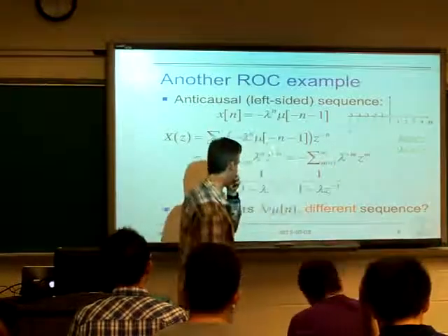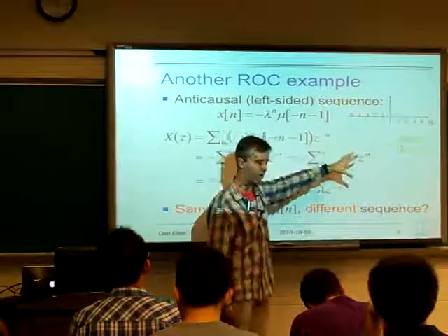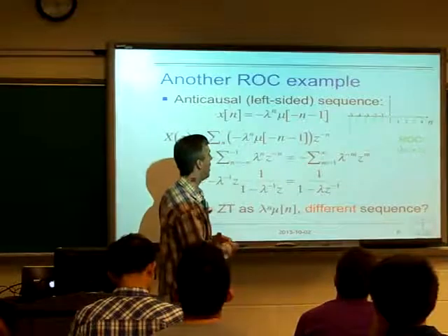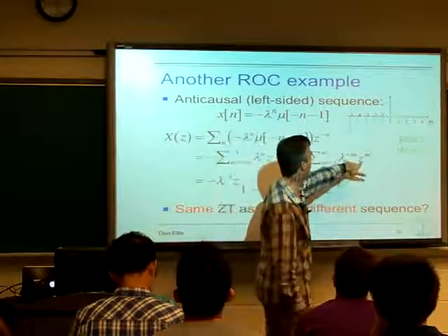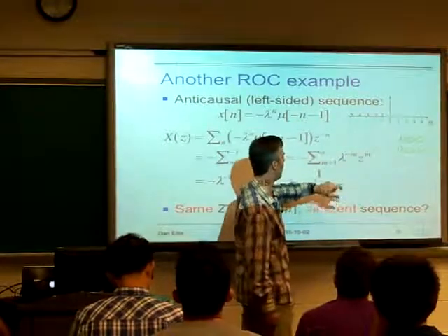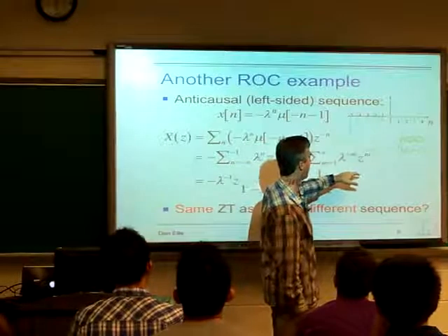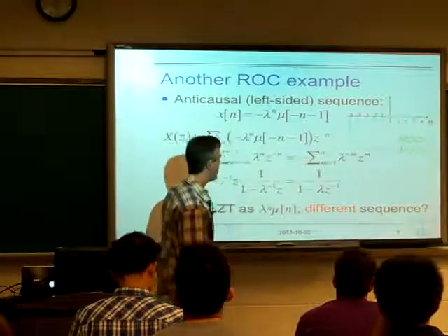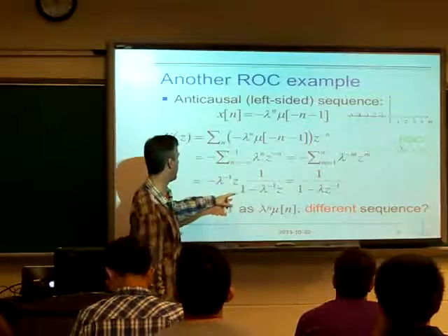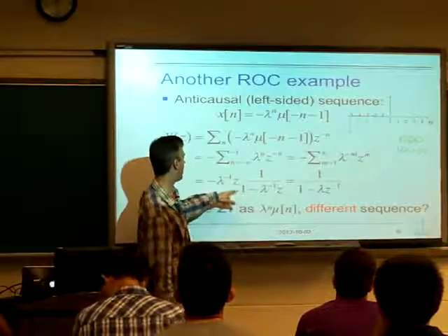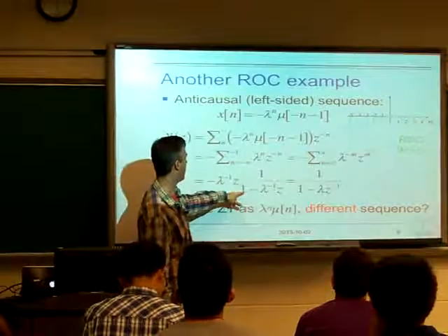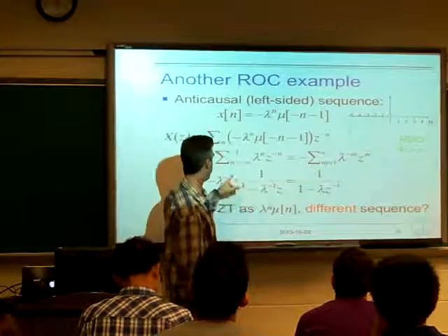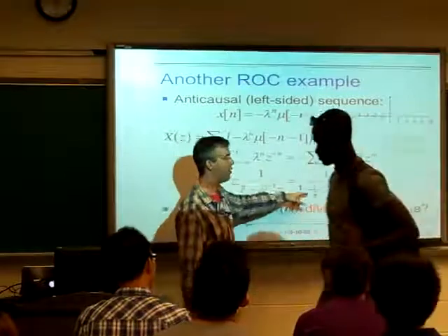So it's the sum from m equal 1 to infinity of lambda to the minus m, z to the m, which we can recognize as something we can solve with our geometric series identity, provided this thing has a magnitude smaller than 1. So provided z divided by lambda has a magnitude smaller than 1, which means the magnitude of lambda is greater than the magnitude of z, it works out to be this. It's starting from power 1, so we get one of these on the top. Then if we multiply through top and bottom, we get this coming out.